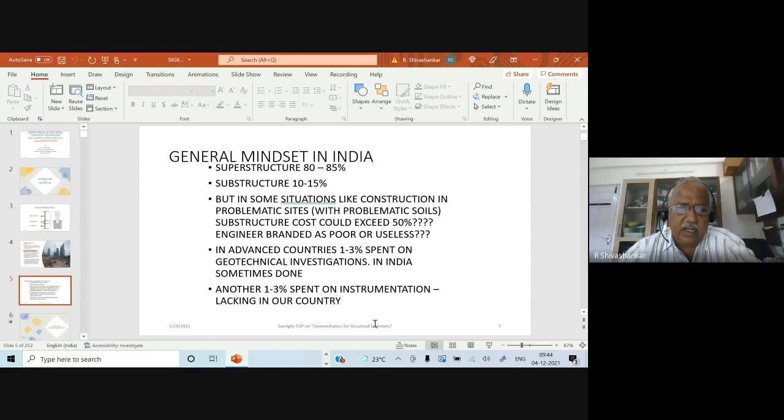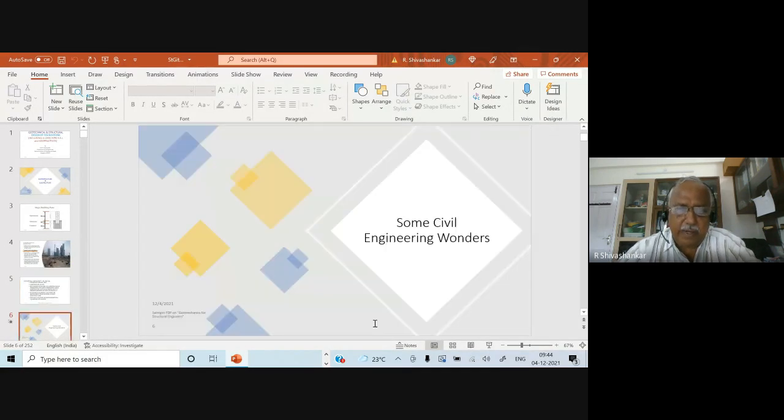So designers most often do the design of superstructure separately, assuming a fixed base, and then the substructure, the foundation design is done without considering the superstructure. So that is sometimes not the real case, not the reality, and then we end up with wrong predictions or over design many times. So in engineering, economy is also very important. So if you use a proper design, we can achieve good economy.